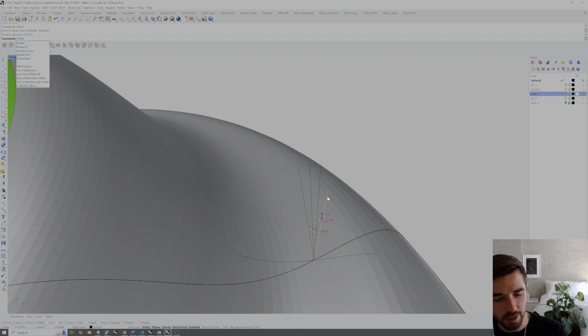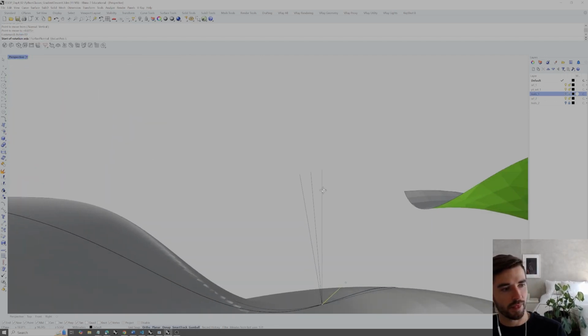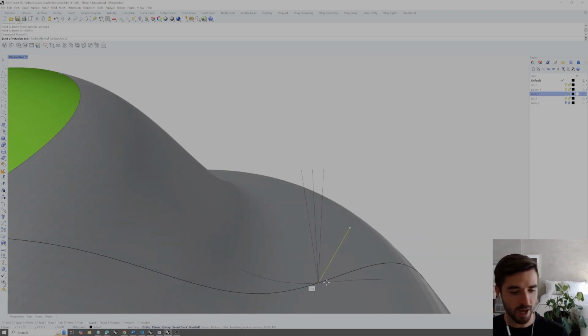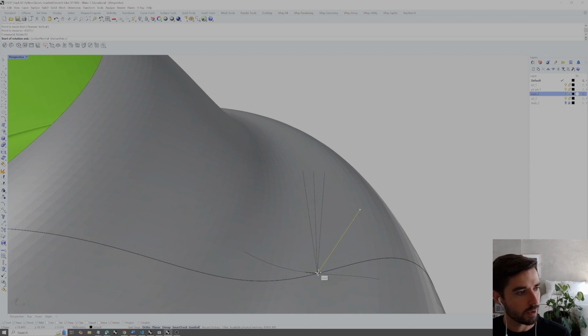Now if I rotate 3D again, because we don't want that vector sticking out, right? It's pointing up. We want the vector pointing down on this slope. So if we use our normal vector here, which is the second vector, as the axis, then we can click on our vector, type 90, and rotate it 90.